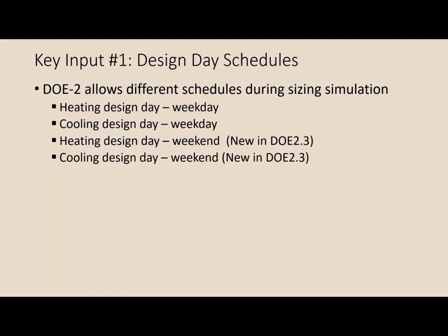Design day schedules existed in DOE 2.2, but there were some expansion in DOE 2.3 with regard to weekends. So in DOE 2.2, you could only specify heating design day and cooling design day schedules that would be applied through the whole week.